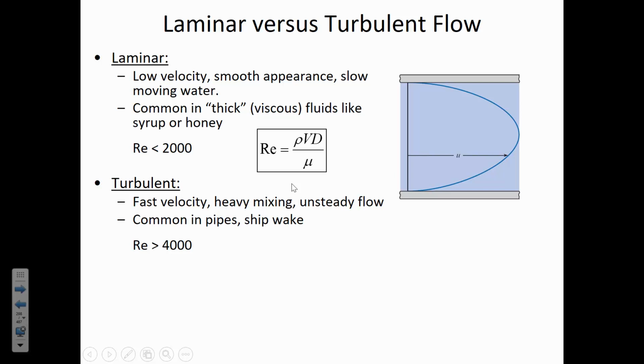So as we open the valve, the velocity is increasing. So the Reynolds number is slowly going up and up. So let's say that now we've crossed the threshold of 2,000, but we came at it from the direction of the laminar side of the dividing line. The flow conditions would stay laminar until there was some sort of a disruption, like if you hit the pipe with a hammer and induced some turbulence, or once you get beyond 4,000. Then the turbulent flow will occur.